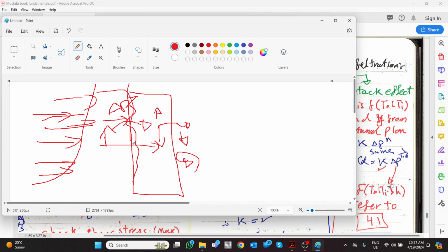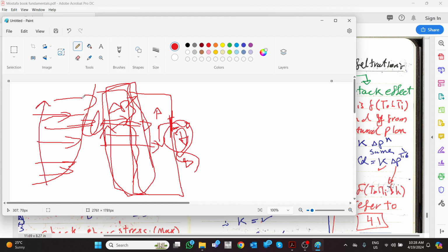But we're going to concentrate on this one to check what the infiltration rate is, because this effect is very minimal, except if you open the window. But if the window is not open, it's okay. Here the pressure is very high, so you cannot assume that even with the window closed there is no leakage. You will have some infiltration air leakage, and it depends on the height, because we know that when you go higher, the wind velocity is higher, and when the wind velocity is higher, delta P is higher.